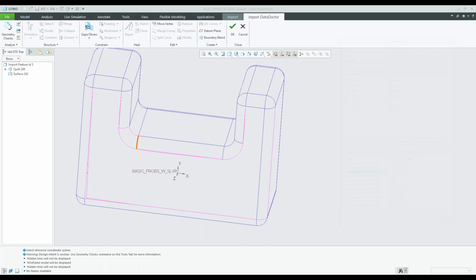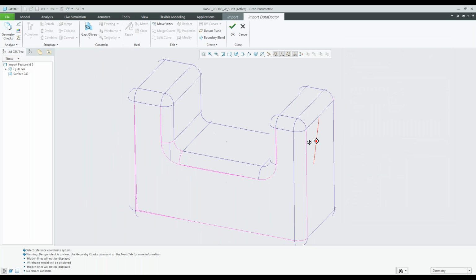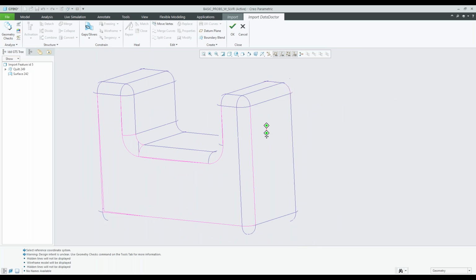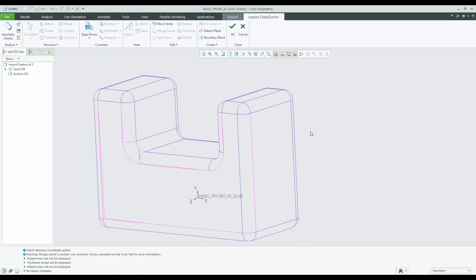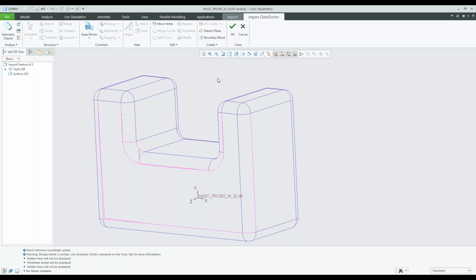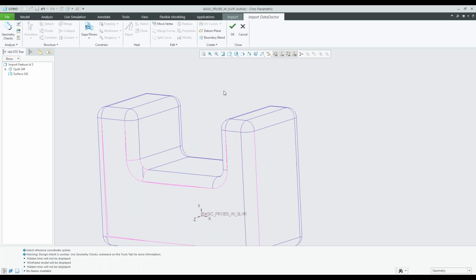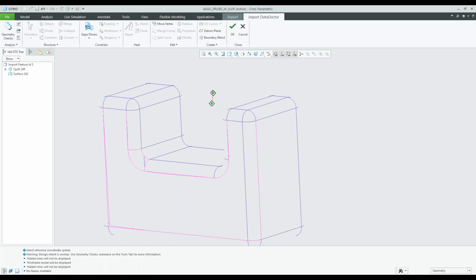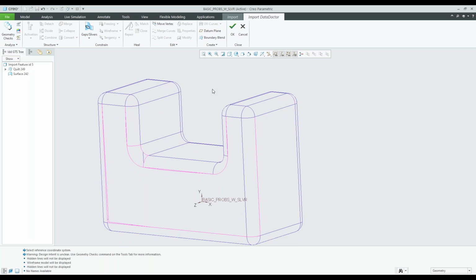And then just one tip that I want to give you guys. A lot of the time you will come into Info Data Doctor. You've watched the webinar, it's easy. Pierre just clicked a few buttons and he clicked on repair, but now repair is grayed out, so you're not sure what's going on. Because of the new Creo 7 and multi-body things, you have to activate, you have to tell Creo where you actually want to work.